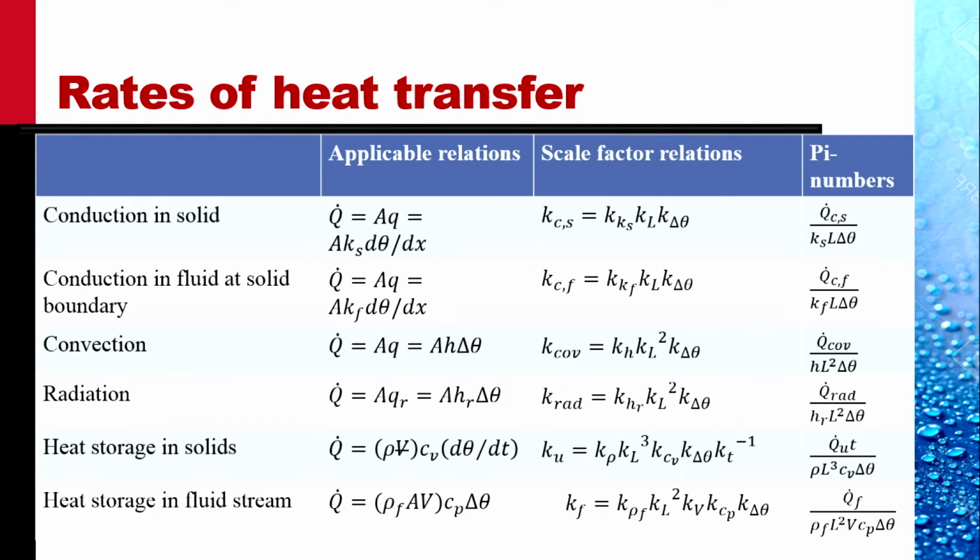So let us consider them one by one. The rule applicable to conduction in solids is the Fourier Law. The rate of heat transfer Q dot is area times the heat flux, and the heat flux is given by the conductivity of solid K sub S times the temperature gradient d theta by dx. Fourier law of heat conduction.